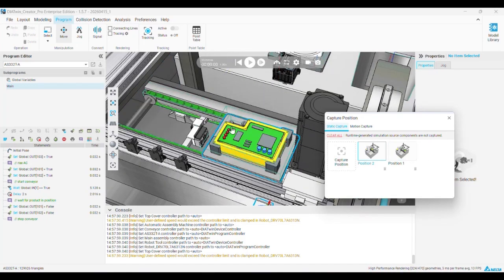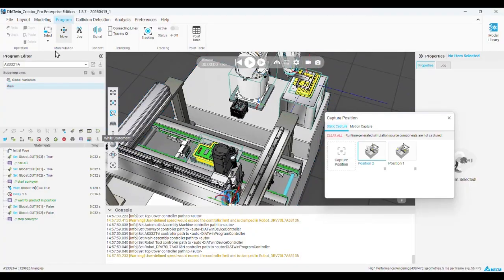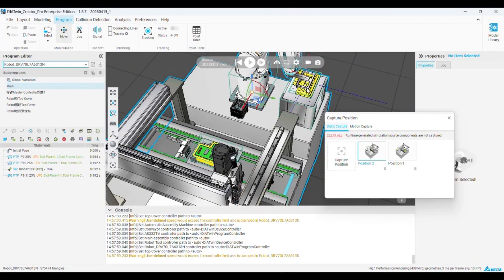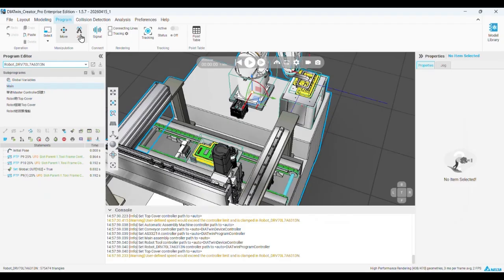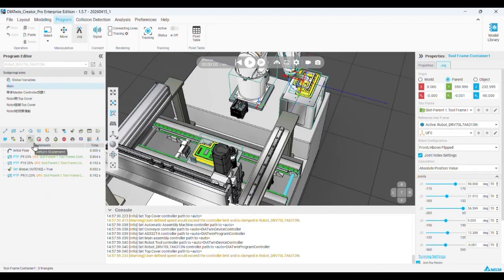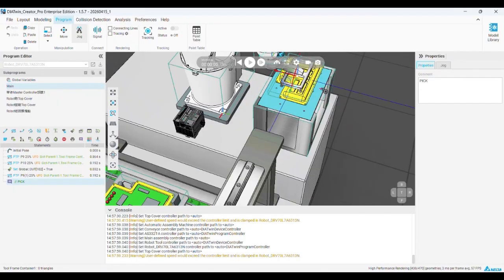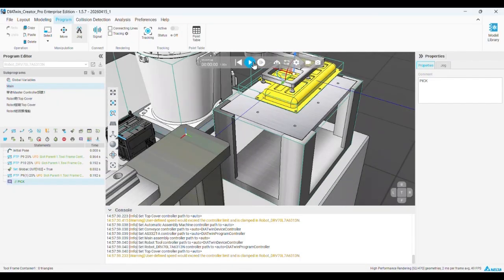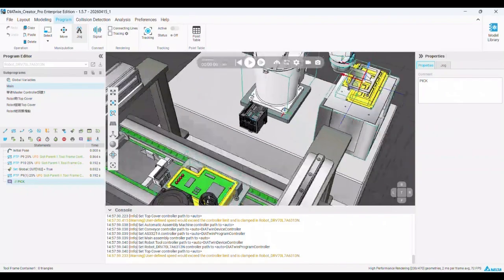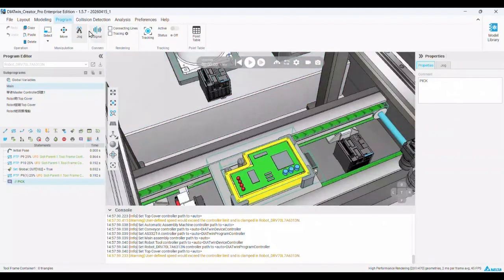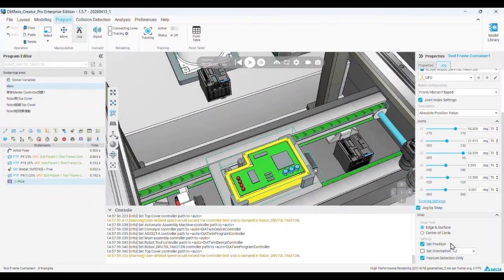So I'm about to use this to teach the robot point. So back to our robot process. I just turn on the drop mode. Right, this one is pick. So we also need to teach the placing points. Before we teach the placing point, we have to know where is the position we need to teach. So maybe we choose drop mode. Please remember to enable the drop by state feature.